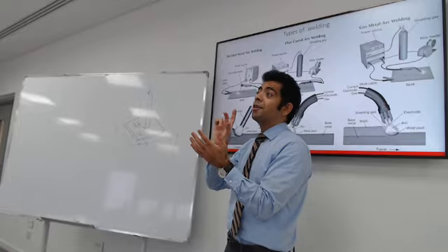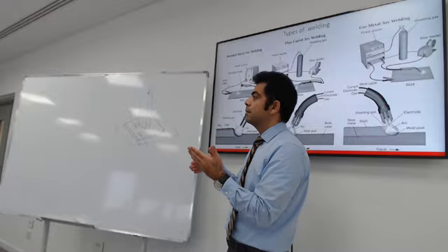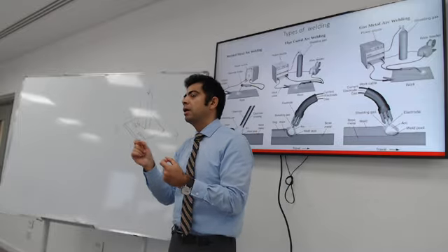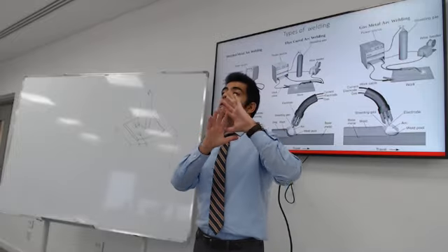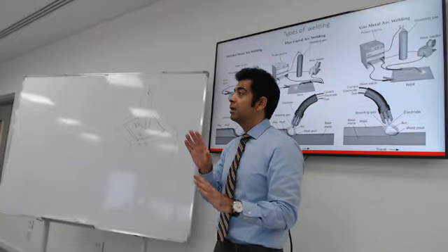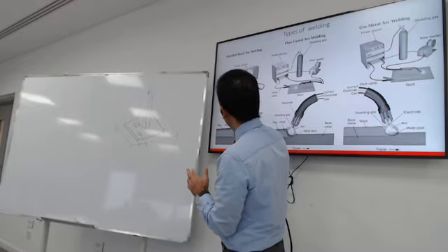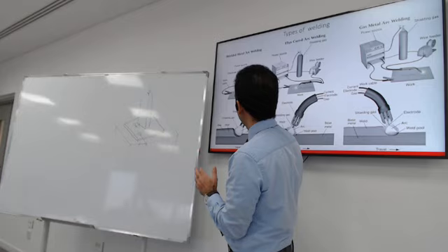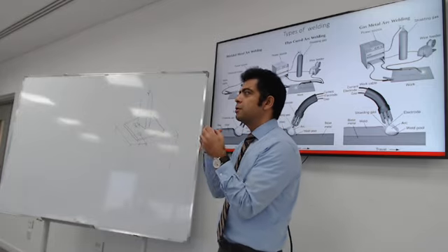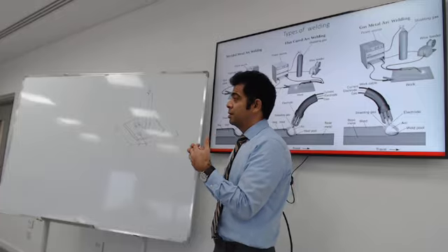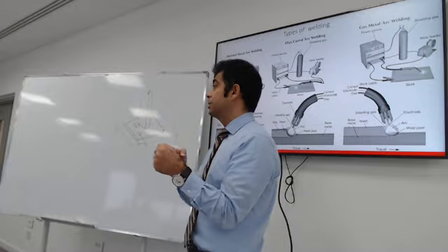Very high temperature will form, and then you will introduce the welding material. How does the welded section compare to the actual steel? Well, it depends on what you do to it. The material or the electrode that you use to create the weld material is usually stronger than actual steel. So failure usually is not going to happen in the weld, it's going to happen in the actual material.